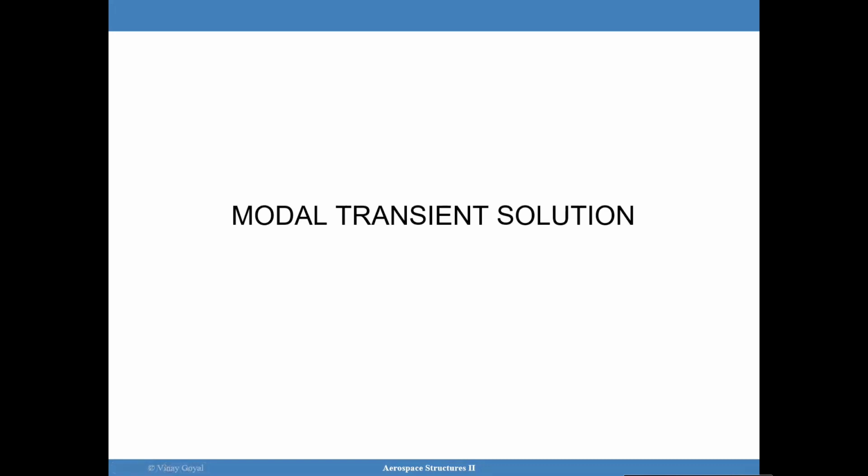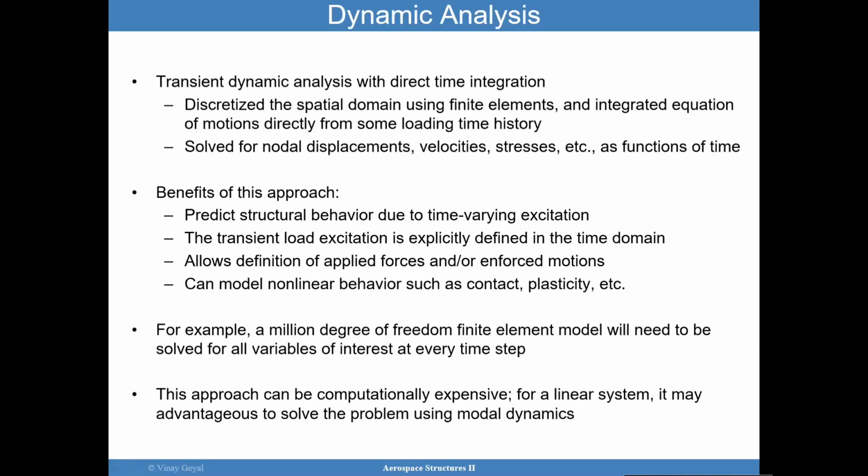So again, a structural system is going to have fundamental natural frequencies and mode shapes that describe the way these structures will vibrate. And the natural frequency basically tells you the number of cycles per second the vibration motion is occurring. And so I'm going to use that to my advantage. I'm going to use a transient dynamic analysis now by using the mode shapes.